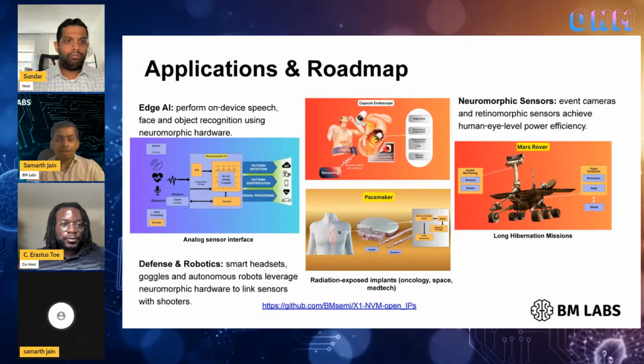For leaky integration, how you can do it in our IP is that our sense amplifiers are capacitive in nature. So you can do integration using a capacitor, and you can use the memory element from the resistive ReRAM that we already incorporate in our X2 IP, right? From a digital designer's perspective, you just have to give the command that you want this kind of behavior. Using the behavioral model you can check, but inside the IP we use a capacitor to integrate and use the resistive RAM as a memory, so that forms a complete leaky integration kind of neuron.